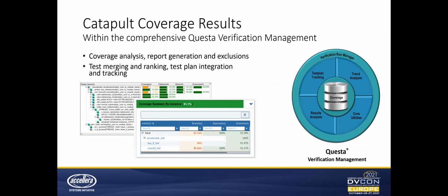Each simulation involving a pre-HLS design that was instrumented for coverage will result in a coverage database, and this comes in the form of a standard Questa UCDB file. Like any UCDB, these can be merged together. We can merge them with a standard test plan UCDB and use them to produce reports or view in the graphical interface for analysis and for exclusion development.